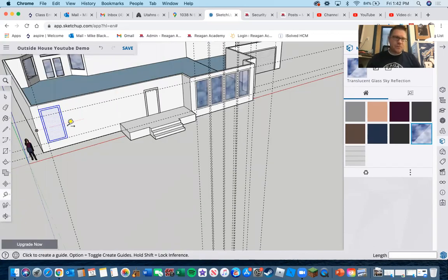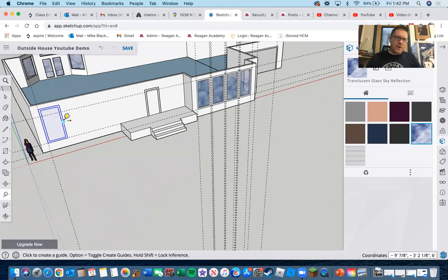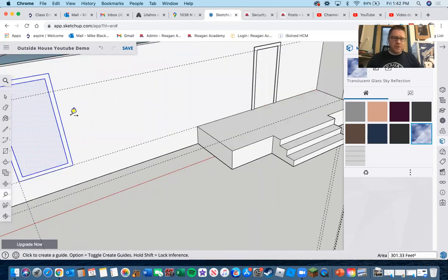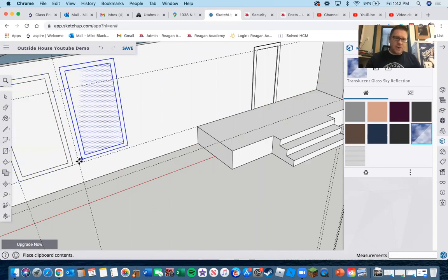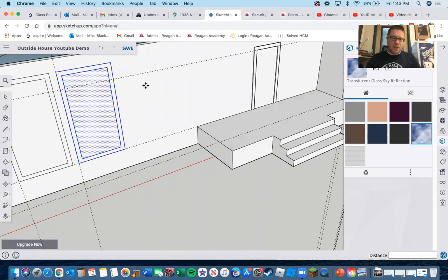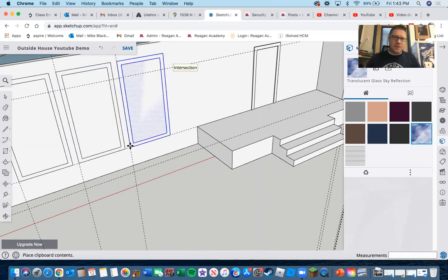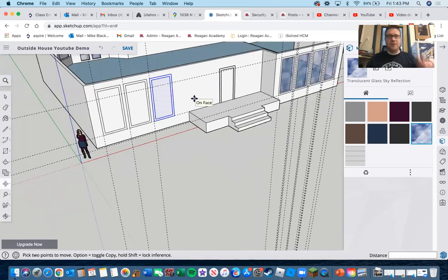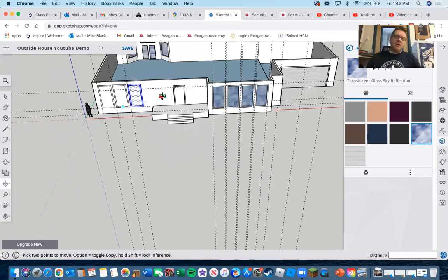So, all right. And then if I wanted to make it so it had the same spacing, I would just come and add a line that's 6 inches. And then I could paste it again, put it right there, do another line with my tape measure, which is T, pull that over 6 inches. Then I could just keep going and copying and pasting all along here until I was satisfied with how it looked. So that would work as well.